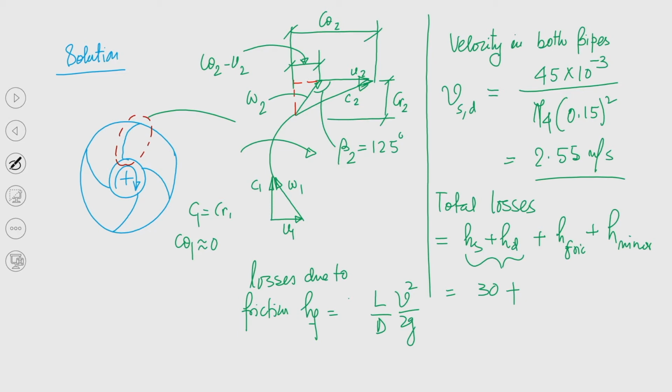Now, here it is very important whether we should consider F or a different coefficient. You have studied that this is the Darcy friction factor. Now, I will be using 4F. This is also very important, that fanning friction coefficient. So, basically F is the Darcy friction coefficient. Sometimes it is also termed as Moody friction factor.